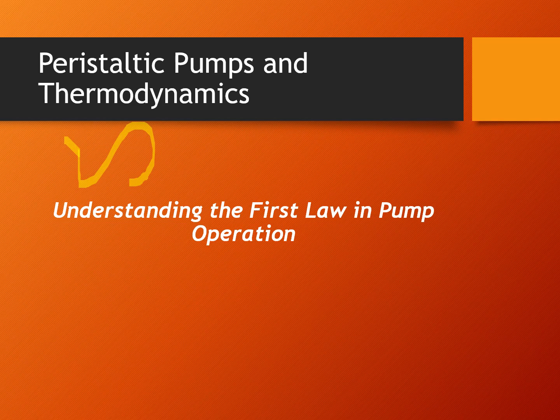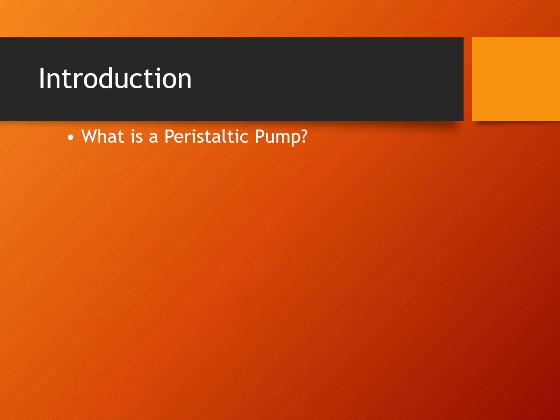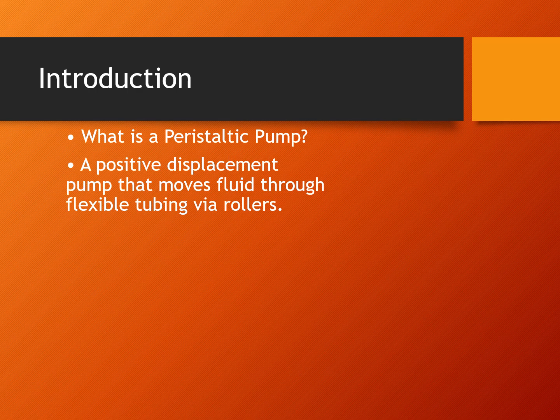Let's begin by defining what a peristaltic pump is. So, what is a peristaltic pump? It's a type of positive displacement pump that moves fluid through flexible tubing using rollers or shoes. These rollers alternately compress and release the tubing, creating a peristaltic motion that pushes the fluid forward.